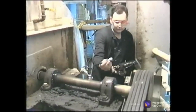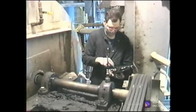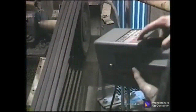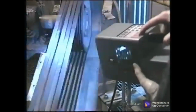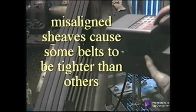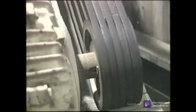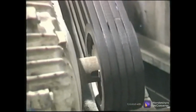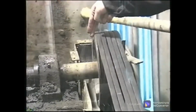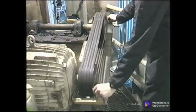The vibration measurements made prior to balancing this fan had high axial energy at shaft turning speed. The belt guards were removed, and a quick inspection was made of the belts while the machine was running. Some of the belts were slipping, causing them to turn at different speeds. This was expected since misaligned sheaves cause some belts to be tighter than others. When the machine was stopped, the belts were inspected, and although they showed wear, the decision was made to reuse them. The alignment check was made on the sheaves using a string.